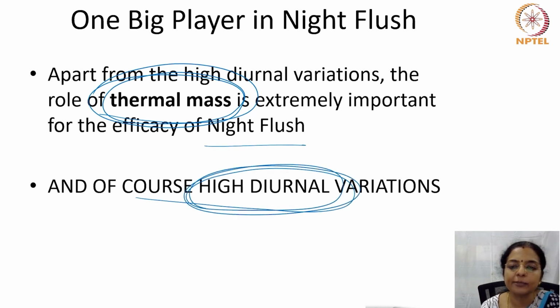So any place which has very high diurnal variations, and where you have a high thermal mass, in that place night ventilation is a very effective indoor passive cooling technique.